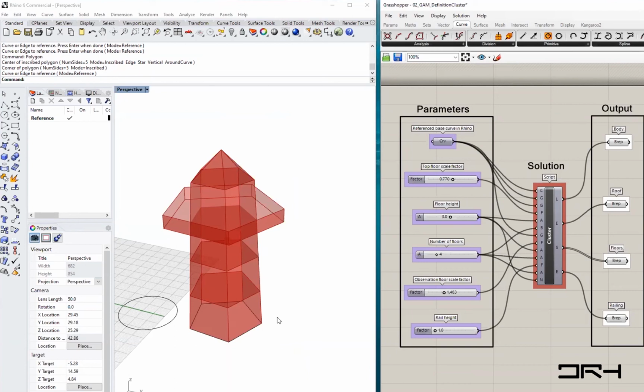Does that make sense? So this is considered 0. But if you have a free-form surface or a free-form curve, then the rate of change is going to change over 1 unit length. When you have a minimum and a maximum, this is the minimum and maximum change in curvature within your whole surface if you take a sampling all across. So that's what the number represents.